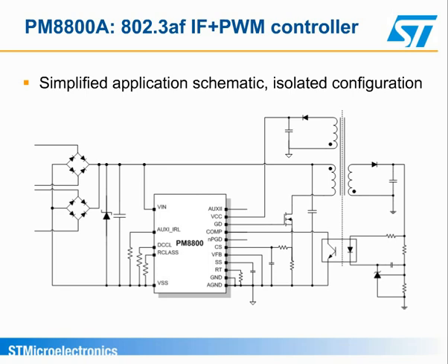It is possible to program the power class, the inrush current limit, and the DC current limit by acting respectively on the R class, AUX1 IRL, and DCCL pins. The source and the drain of the internal hot swap MOSFET are respectively VSS and GND.